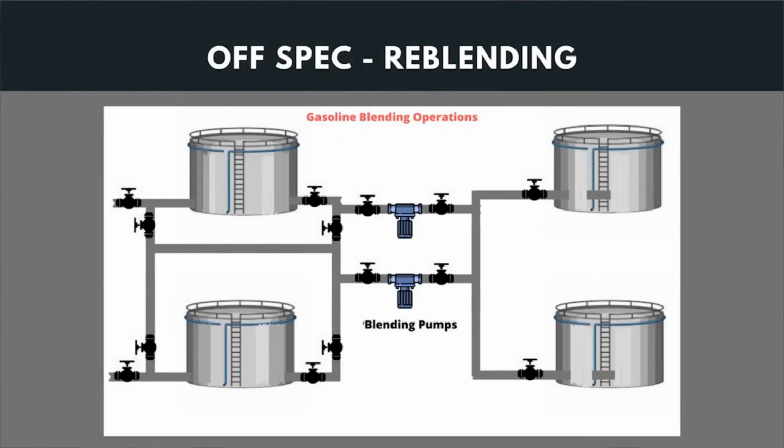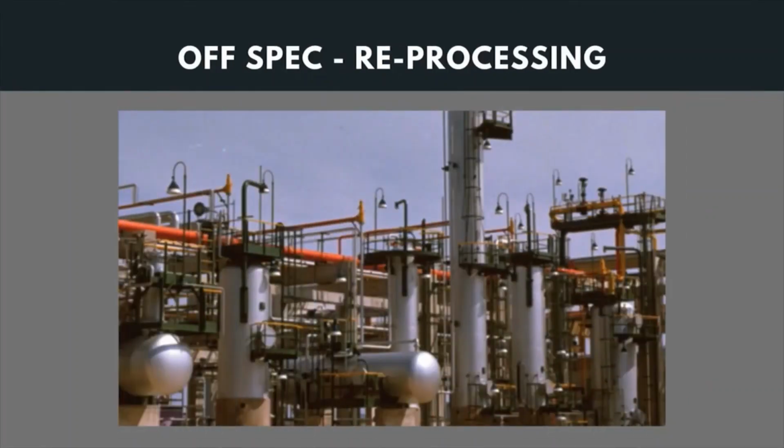Whenever a tank is full with the product, samples are taken to the lab, and based on that, the quality control lab gives a clean sheet for all the specifications. It generates the certificate of quality, and then the product is pumped out to the market. If one single test fails, then it means off spec. It cannot be taken to market. In that case, you have to do reblending or reprocessing. Both are time consuming activities. In some cases, you may have to reprocess where you cannot do the course correction by reblending.